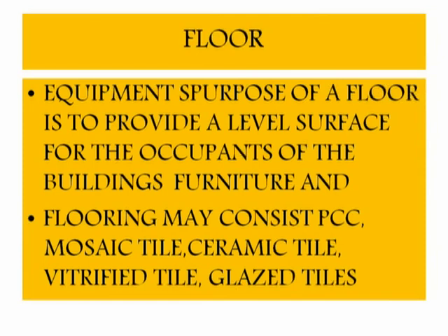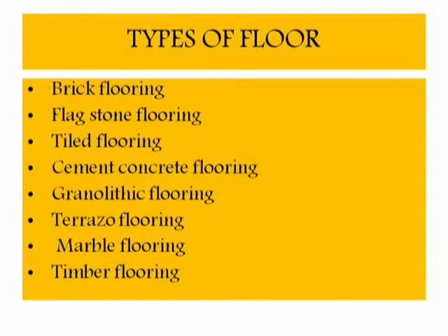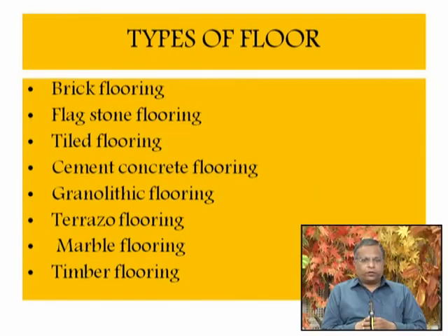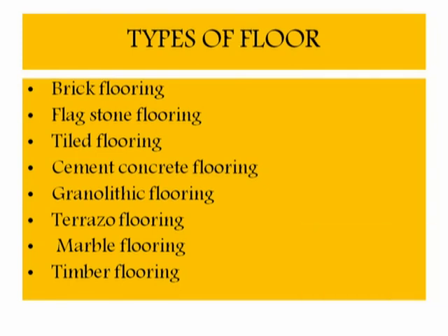The plane surface which is constructed, over which the equipment or the persons are living, is known as a floor. Flooring may consist of PCC, mosaic tile, ceramic tile, vitrified tile or glazed tile. The types of floor are: brick flooring, flagstone flooring, tiled flooring, cement concrete flooring, granolithic flooring, terrazzo flooring, marble flooring, and timber flooring.